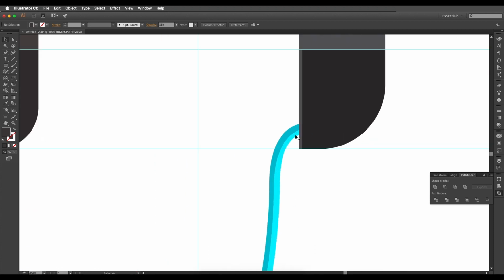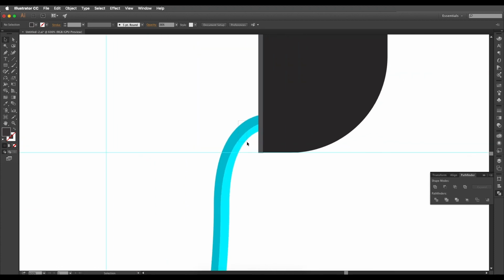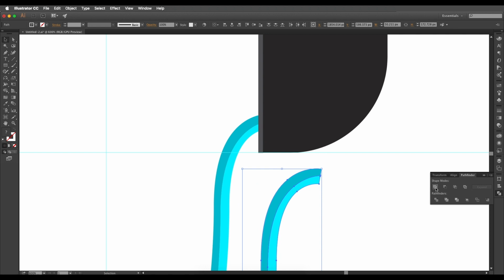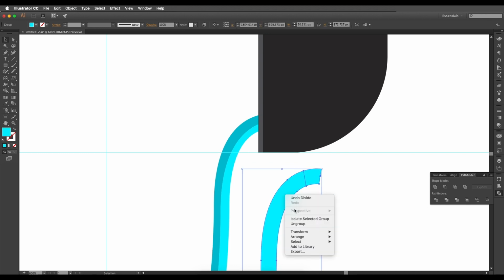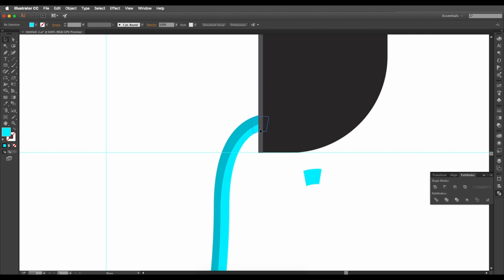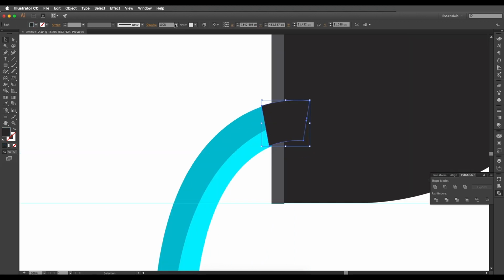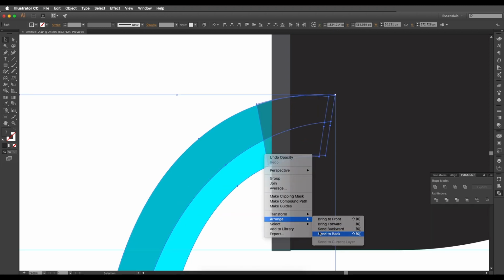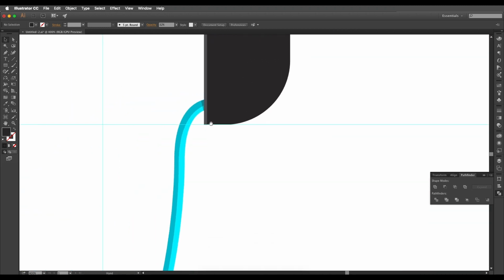We'll do the same over here, but in a different way. Select these and create our duplicate, then combine them together. Then line segment, click and drag and just cut it over here. Divide them and just delete out the lower portion and place this back to its position like this. Change the opacity around 30% like that. Arrange it to back, and here it is.